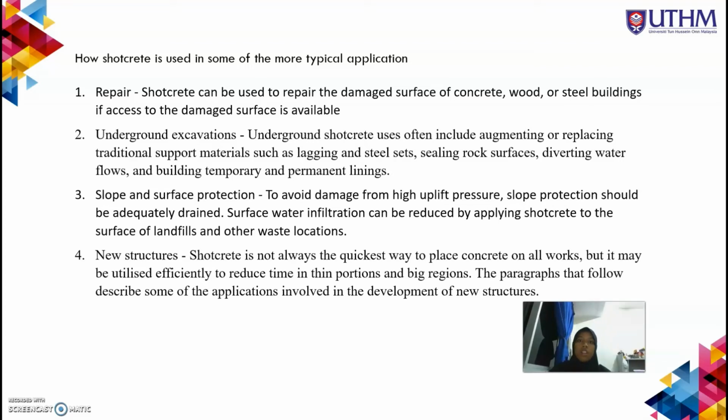Third, slope and surface protection. To avoid damage from high uplift pressure, slope protection should be adequately drained. Surface water infiltration can be reduced by applying shotcrete to the surface of landfills and other waste locations.